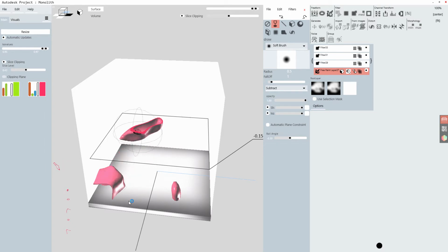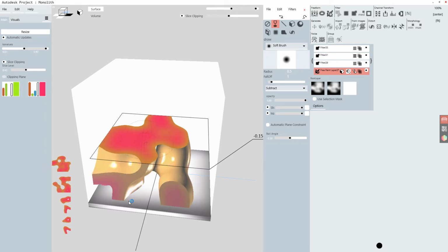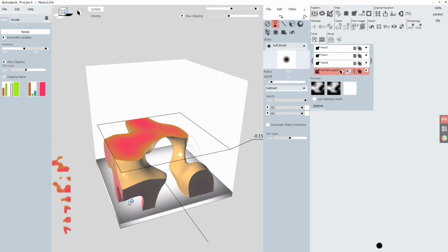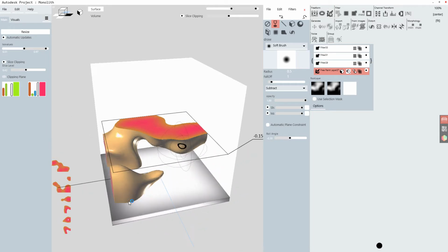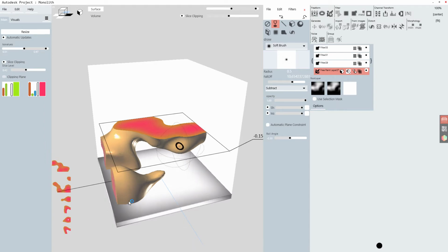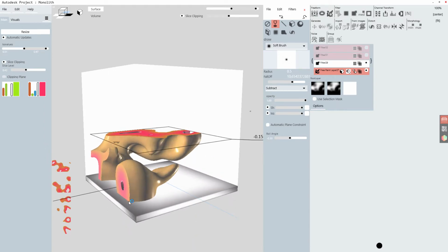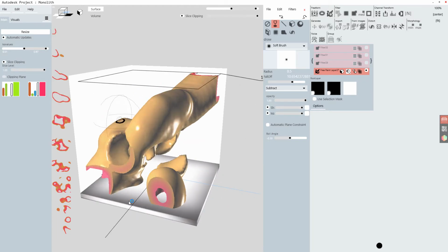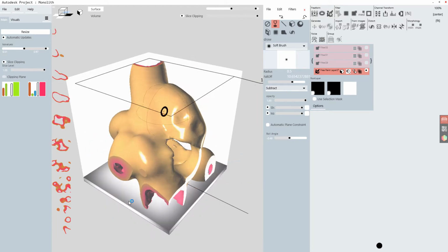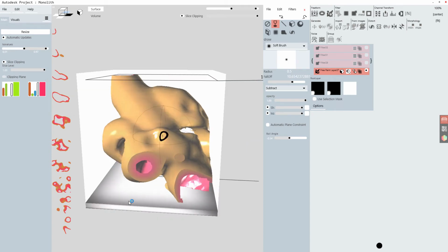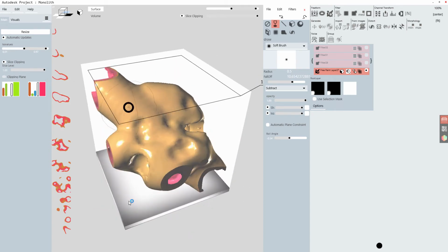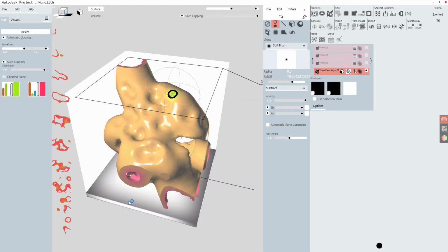You will be removing parts from your geometry, kind of carving out. And you can change the falloff of the brush, so you make smaller tweaks into your geometry. If you set it really fine, it's something like you would do in ZBrush, where you put in holes and make bumps here.